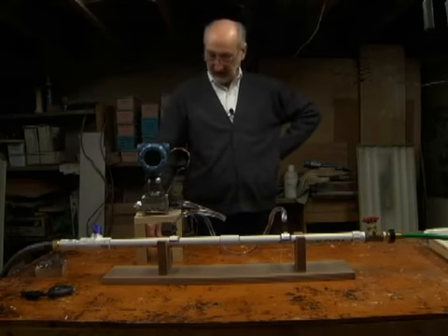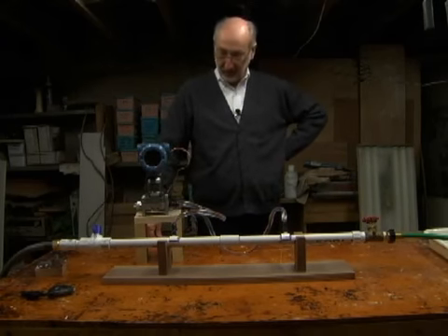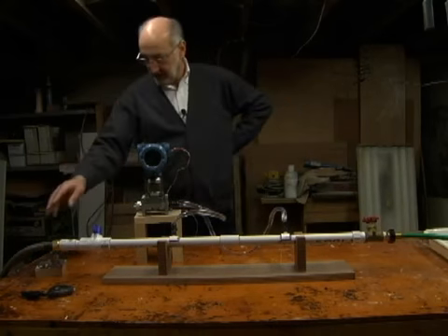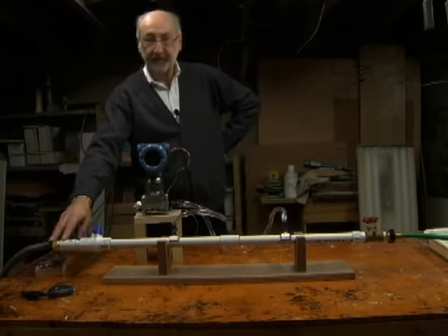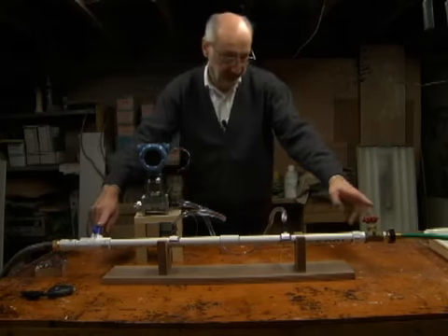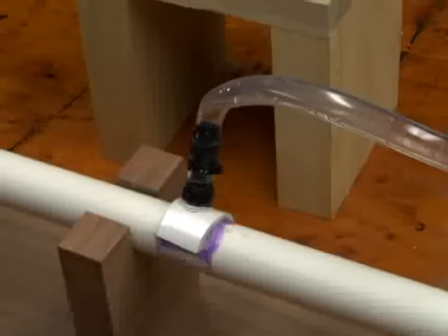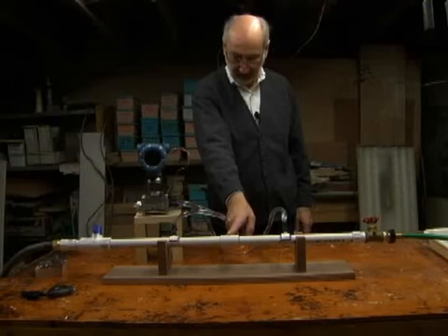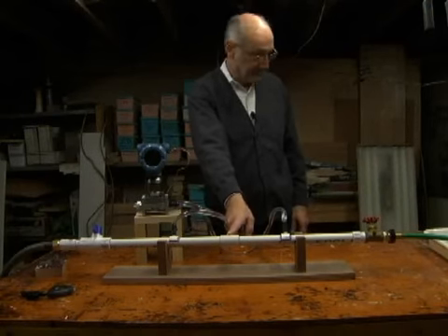This is actually a very sophisticated flow meter here in front of me. What we've got is a water supply, happens to be by garden hose, coming to a shutoff valve and then to this straight section of pipe. What you'll see is we have two impulse lines connected to our 3051 differential pressure meter. Then there's also this union here in the middle of the pipe, this coupling.